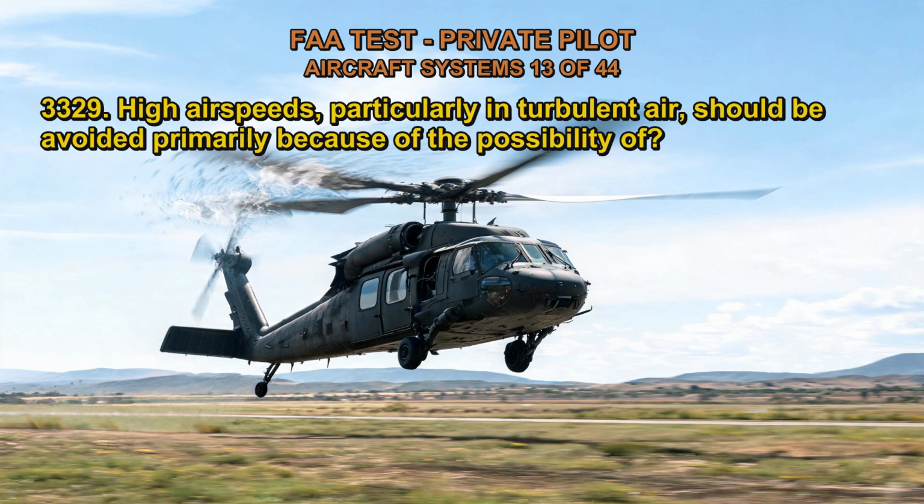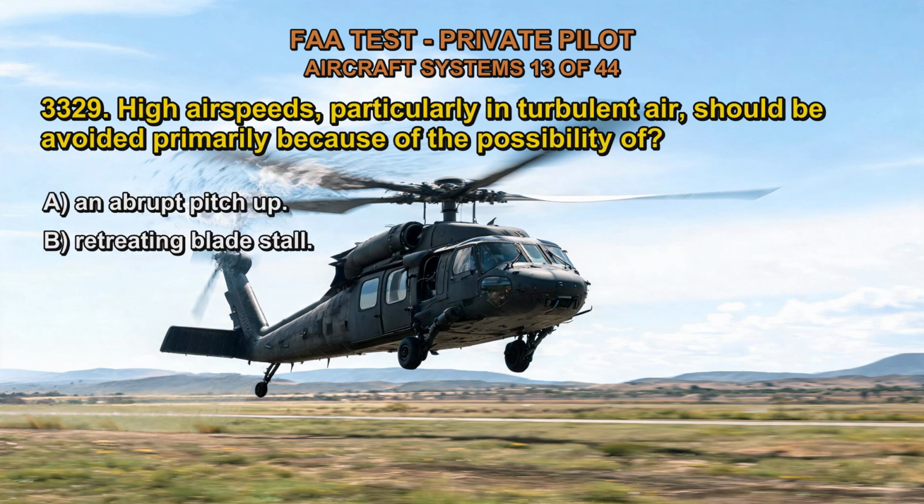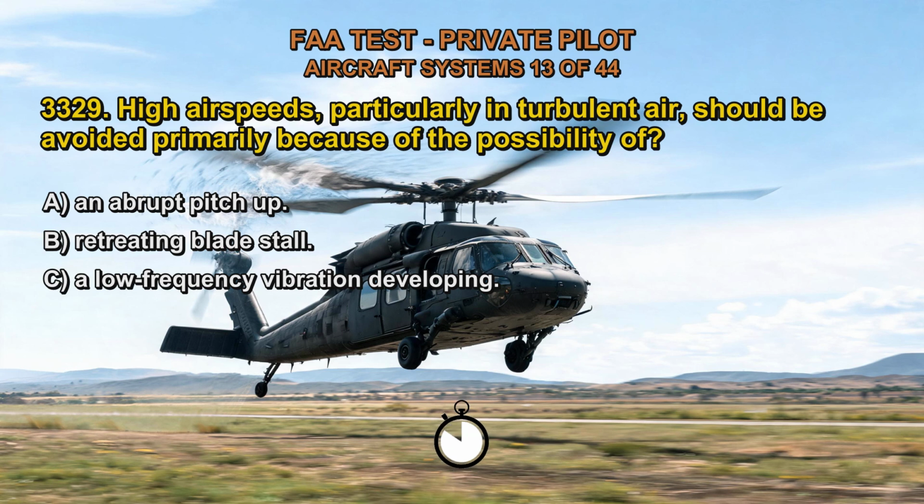3329. High airspeeds, particularly in turbulent air, should be avoided primarily because of the possibility of A. An abrupt pitch-up, B. Retreating blade stall, C. A low-frequency vibration developing. The correct answer is B.